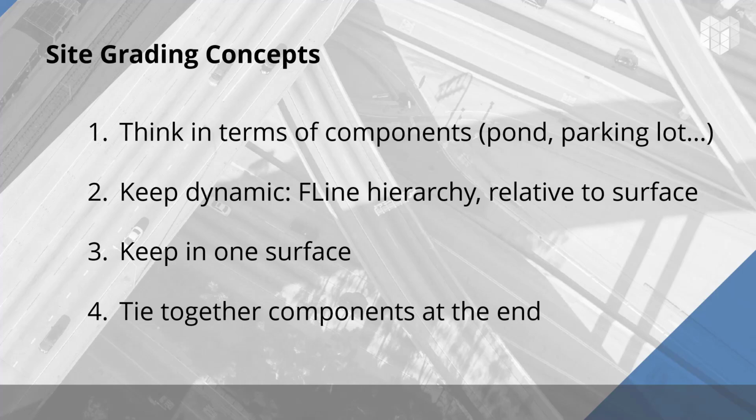And finally, after you've graded out those components, then tie things together after the fact. Right? A spillway from a parking lot into a pond, tying into an existing curb line, something like that. All those kind of tie-in components. Do the primary grading first.